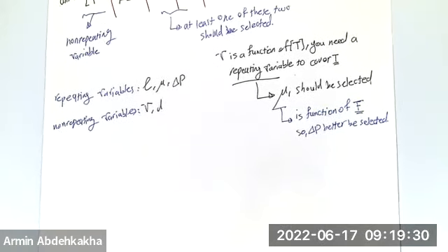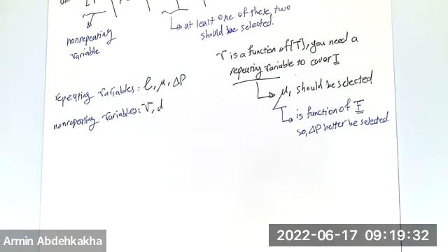That's why these known non-dimensionalized parameters like Reynolds number, Weber number, and the rest are important. And it's better for you to select a set to finally have those Pi terms, right? But mathematically, again, there is no unique solution, but there is a better solution, okay?